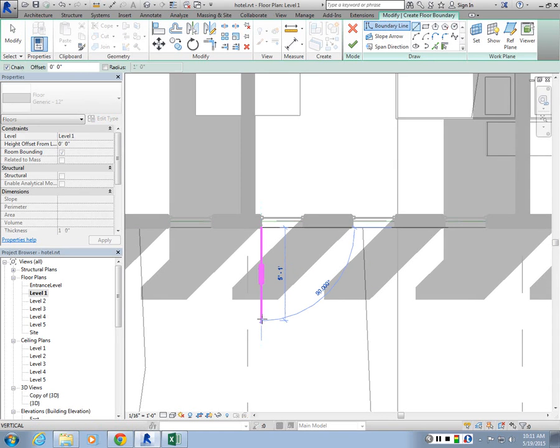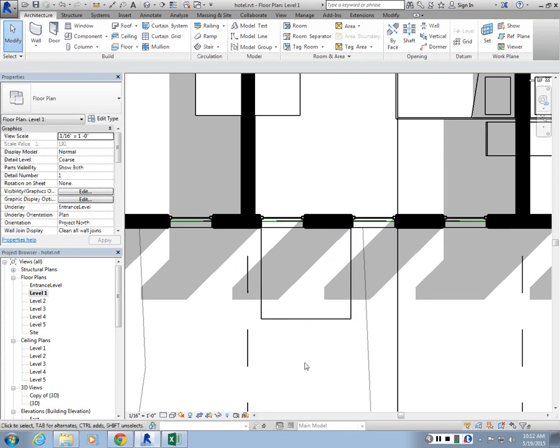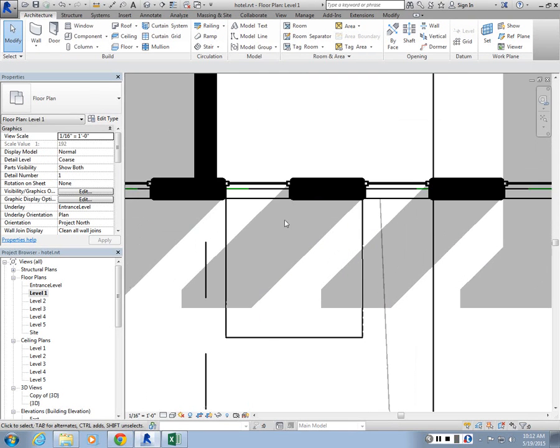So let's say we have a balcony here at 5 feet. So it's a bit larger than a French balcony. And then I'm going to go over and capture this guy as well. And then this. Going to hit check. So now I have a balcony slab there. The next thing I'm going to do is add a railing to it. So I go to railing.